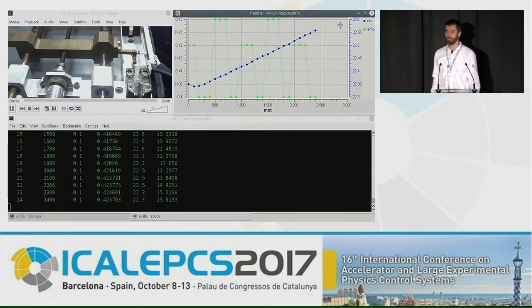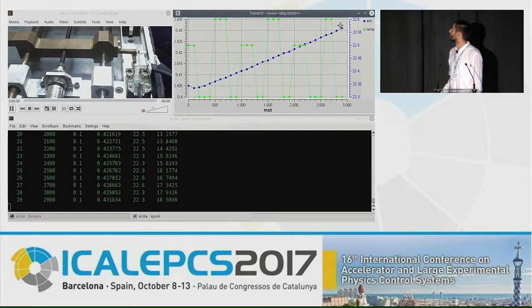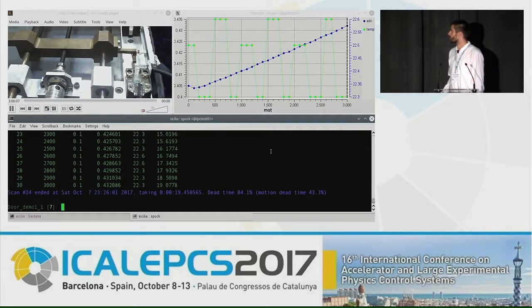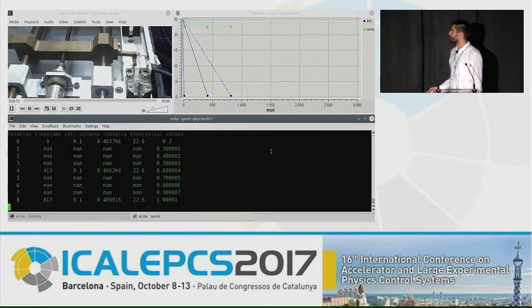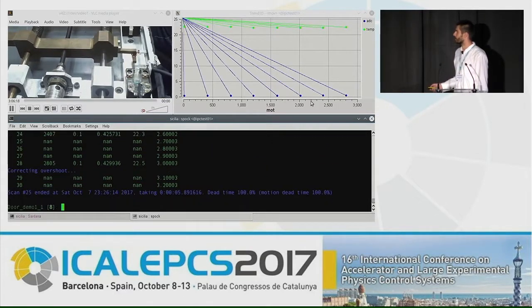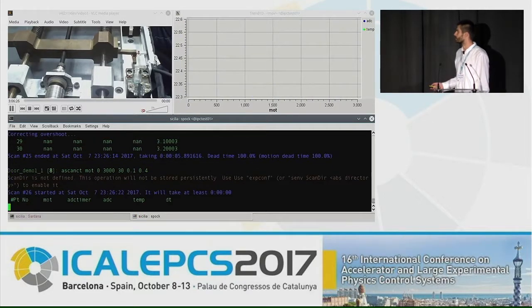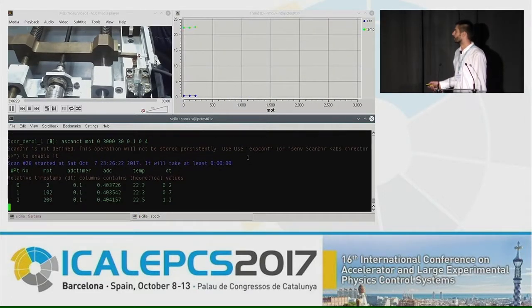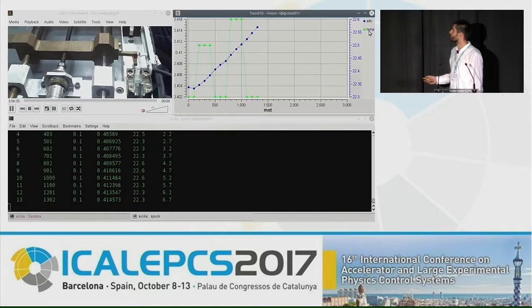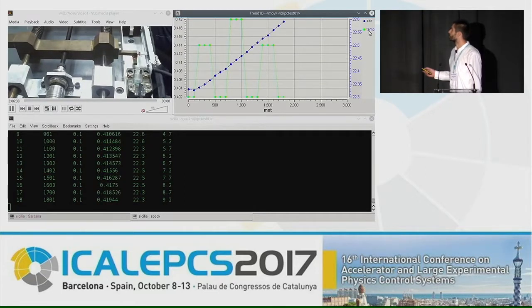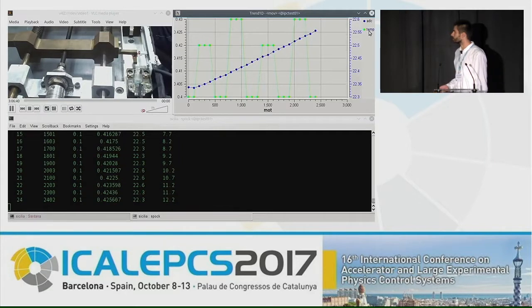With exactly the same configuration, we can execute the continuous scan, which we will now proceed to do. In this case, we use the default configuration, which is the software synchronization. We just changed the name of the scan, and we can see that with the same parameters, the experimental channels cannot follow the rhythm of the scan because of the software state transition necessary. So we have two options now, either to enable the interpolation of the data or to add an extra latency time, which we have added here. So now we are executing a continuous scan, so the motor does not stop, and we are able to see on the same online plot the result of the scan.